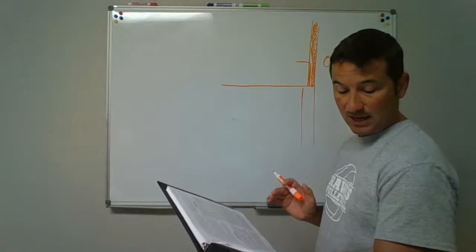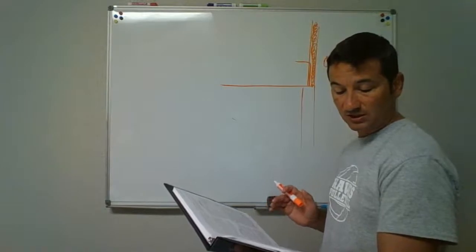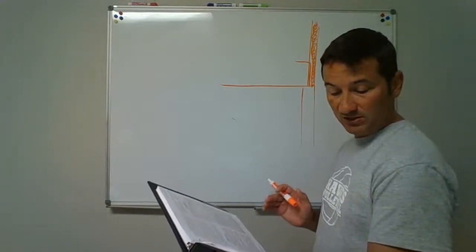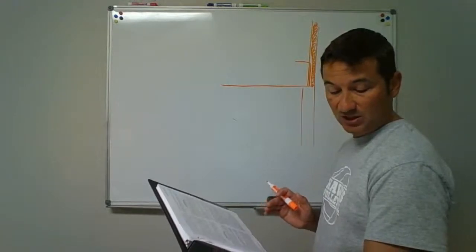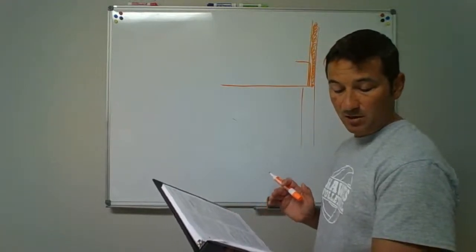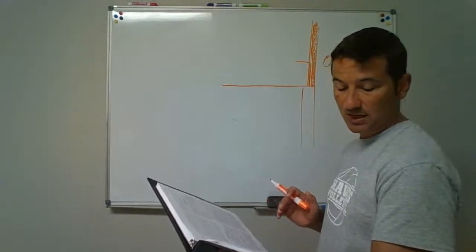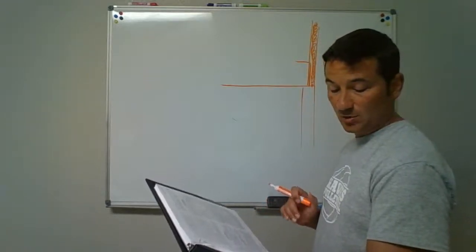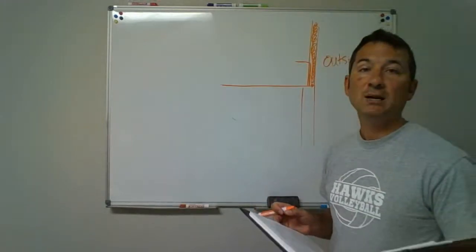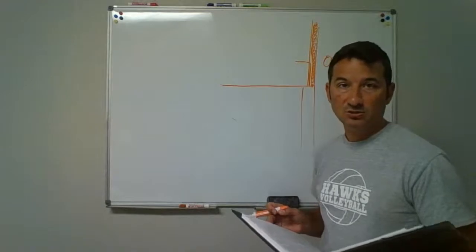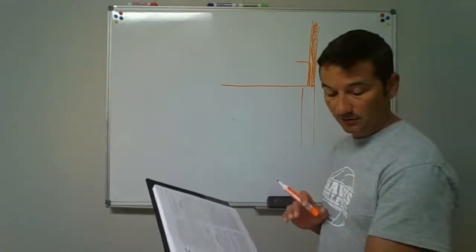In unconditioned attics, unconditioned utility rooms, or any other place subjected to freezing temperatures, unless adequate provision is made to protect such pipe from freezing by a minimum of R6.5 insulation determined at 75 degrees in accordance with ASTM C177. So you can get insulation to pipe wrap them if you needed to. It says, or otherwise, leave them out of those areas. We don't want anything freezing.